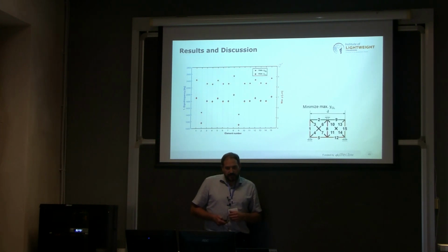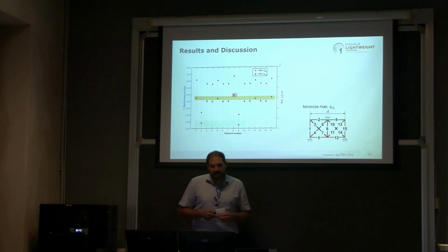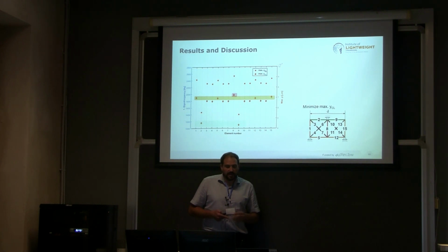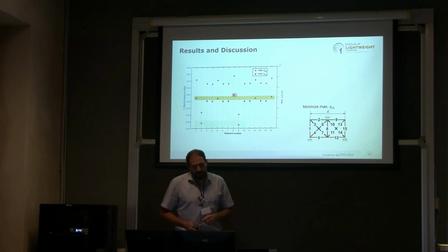And if you look where the deformation is minimal, it's a good idea to put the actuator on position 2 and 9. And of course, it's not a good idea to put the actuator on position 8 or the orange positions, as they are perpendicular to the control distance or constrained within the supports.